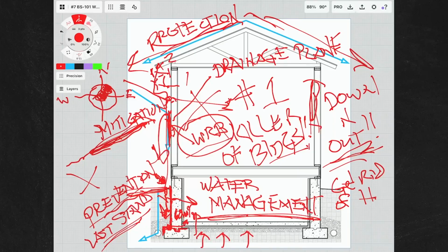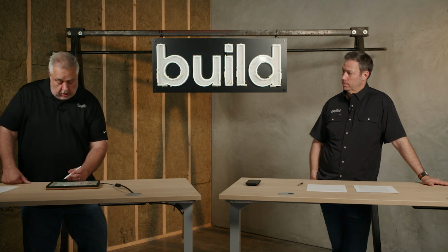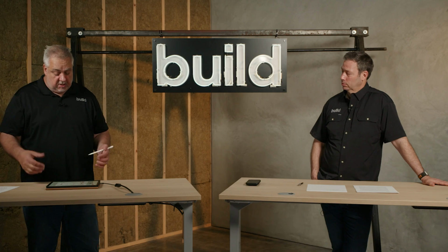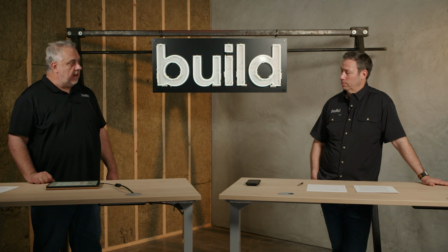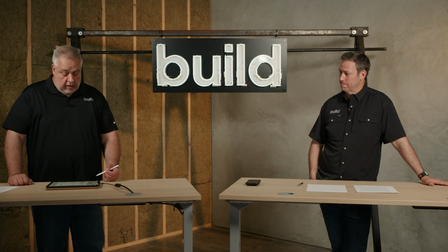And on a recent project of ours, there's a company that makes this little bentonite clay cube, and you can put it right down in there, and just like you said, that clay expands. Well, the minute that gets wet, it expands and basically seals up that joint. Kind of a cork in the wine bottle feeling there. Exactly.